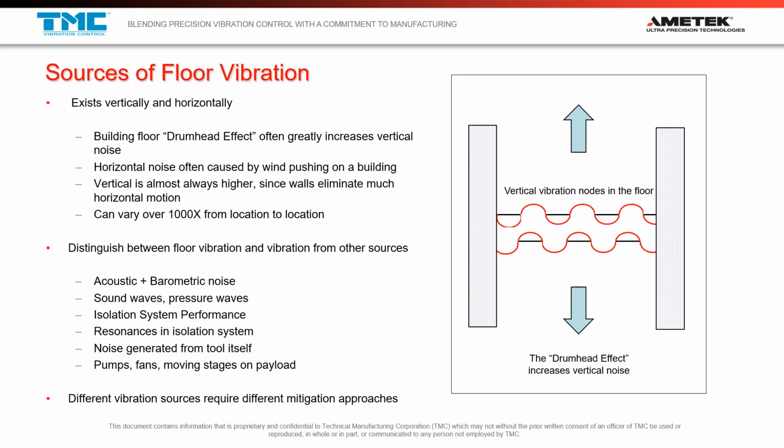It's going to travel through that instrument at very fast speeds to do whatever operations need to be done on it, usually metrology, optical metrology or interferometry. And the motion of that wafer through the instrument as it starts and stops induces a lot of vibration, which needs to settle in time for you to do an accurate measurement. It's a really classic example of self-generated noise.